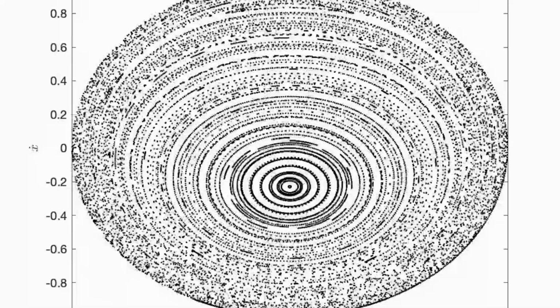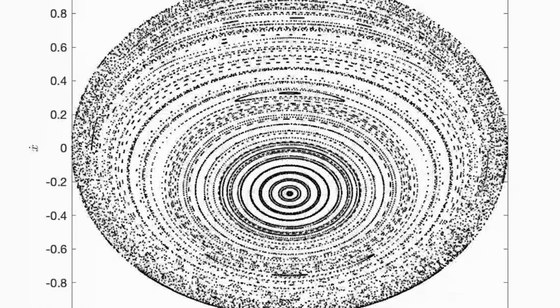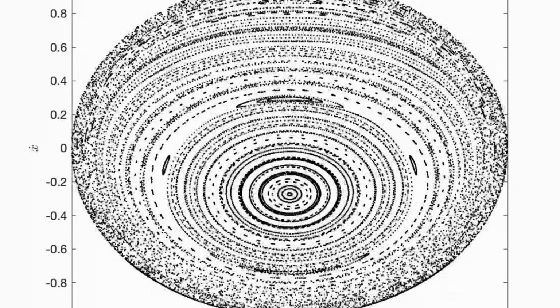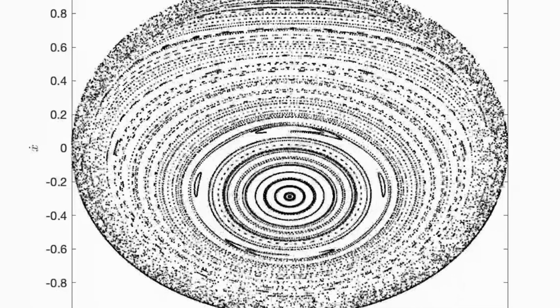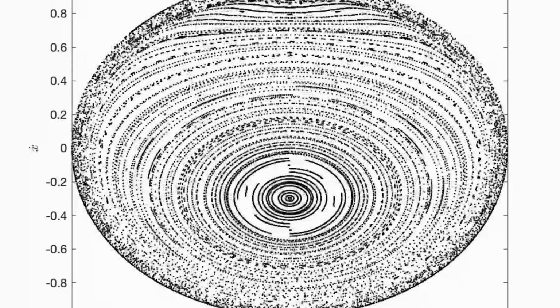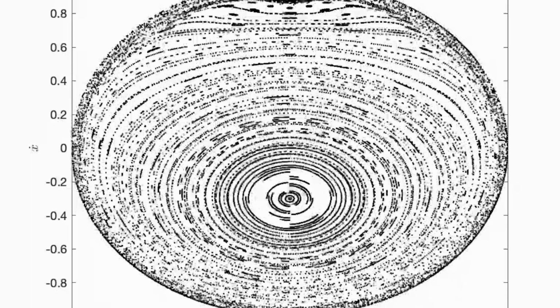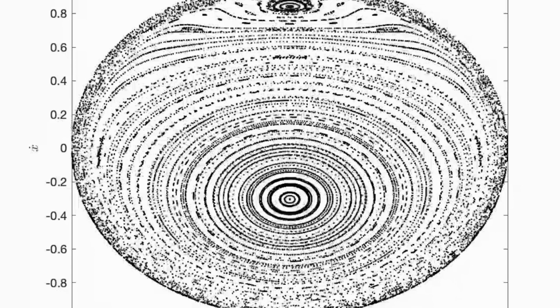We'll see some more interesting stuff up here. Here is actually the emergence of like a 4-to-1 internal resonance. It actually switches between a 4-to-1. You can see there's 2 fixed points, so this is a 2-to-1. Here is back to these 4, and so forth. Here is still a 4, back to 2, 4, 2, and so forth. Here we're getting these quasi-periodic responses. Again, we're not computing enough. Some interesting stuff has been happening up here. There's actually kind of the emergence of maybe a 3-to-1 over here, or maybe just some quasi-periodic orbits.